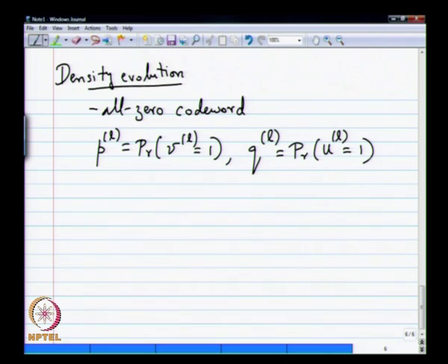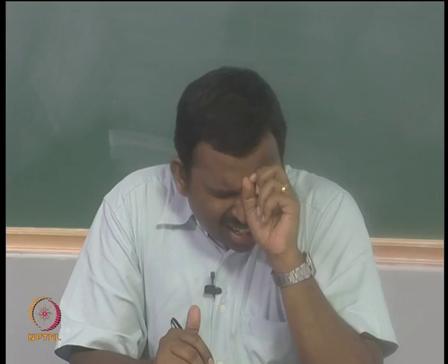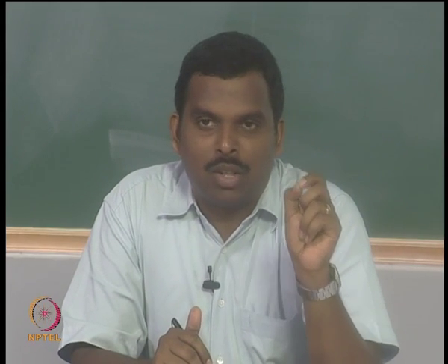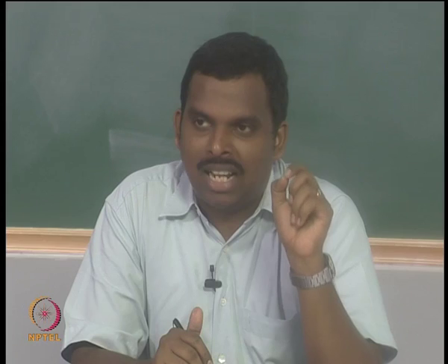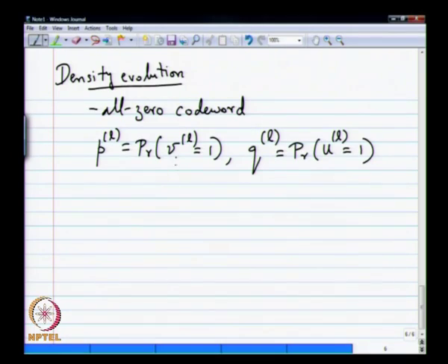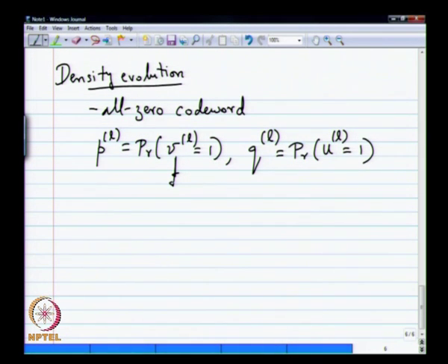Okay. So now comes a crucial point in defining VL and UL. Okay. So in the regular case, I really had no problem in assuming that VL and UL were IID, right. That was a crucial assumption, right. If you remember in the analysis, we had to assume that VL, so the message on a set of edges. Okay. So one of the crucial assumptions was, in the Lth iteration, VL is what? This is the random variable that denotes the message from bit nodes to check nodes.